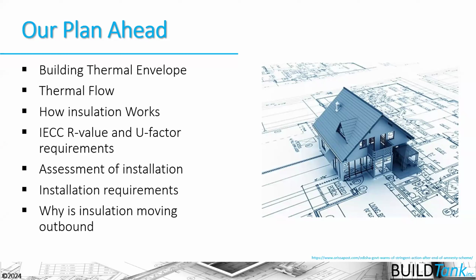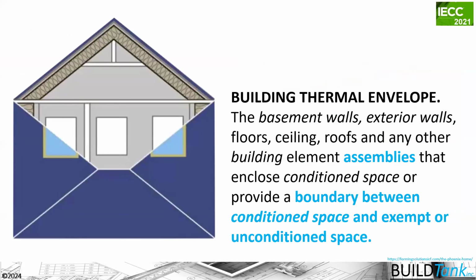We're not going to obviously have time to go over all of them, but ultimately we're going to be talking about why the IECC wants us to move insulation outbound, outside of the cavities to the exterior of our buildings. So to begin with, we have to have a pretty clear understanding of the building thermal envelope.